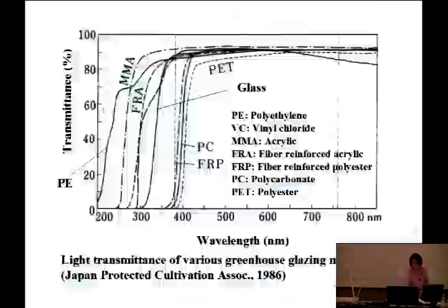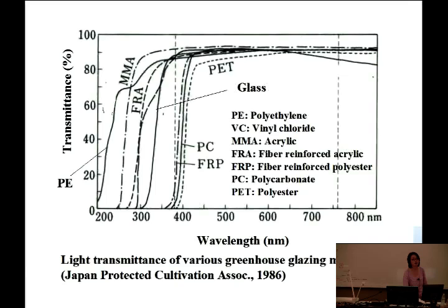So that would be an argument to use polycarbonate-type greenhouses. You could do solid sides and walls, but then cover it with diffuse material. That's right, more light. But that is probably losing a lot more light because of the diffuse property, because it's a PE material, so total transmission is less than clear plastic.